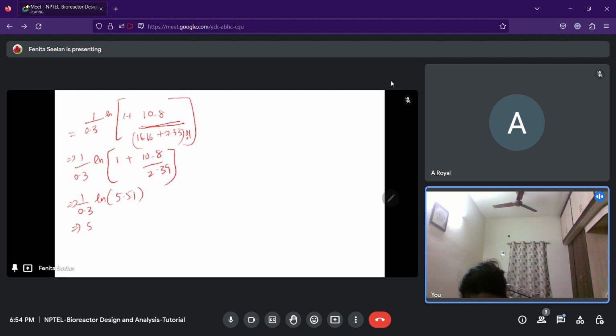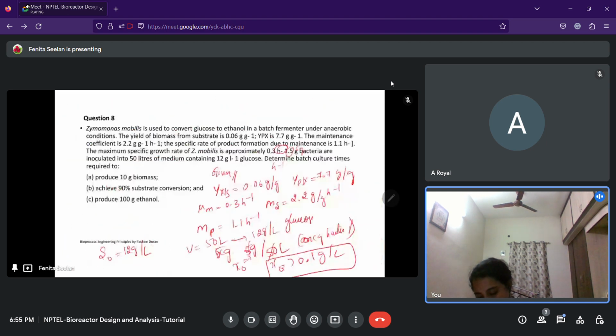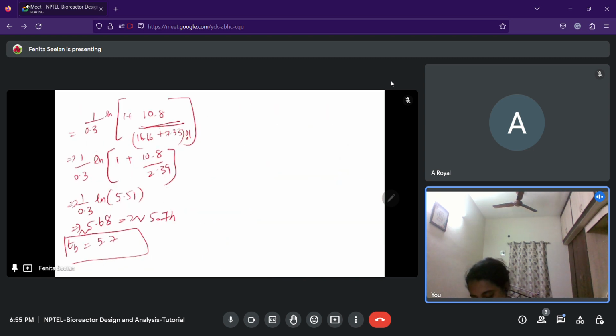Should be 5.68 something. We can approximately say that it is 5.7 hours. So the answer for the batch culture time required to achieve 90% substrate conversion is 5.7 hours. The unit is important.